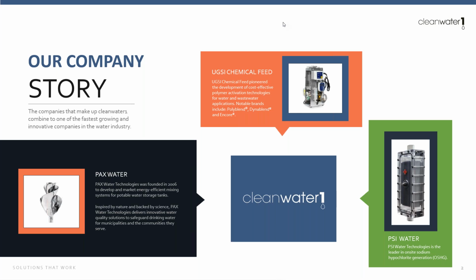We looked at a few different types of aeration, including diffused aeration, spray aeration, and after I got to PAX, we ended up doing a lot of surface aeration. So we'll review all these different types of aeration technologies to strip THMs today. We'll go through the science of trihalomethane removal. But before we get a whole lot further along, I wanted to introduce Clean Water One as a company.